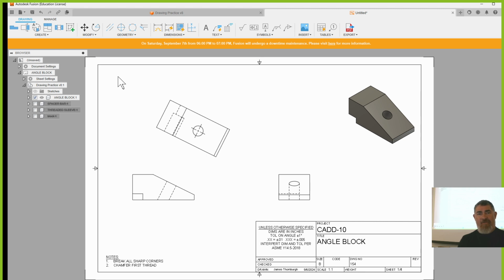Standard says that each view is independent and you don't extend between views. Just the alignment of the views shows you that things are lined up. Some people will make center lines go through to try and show it's the same hole on both sides, but that's wrong. Don't do that. It's a good question. Okay. So any other questions? All right.